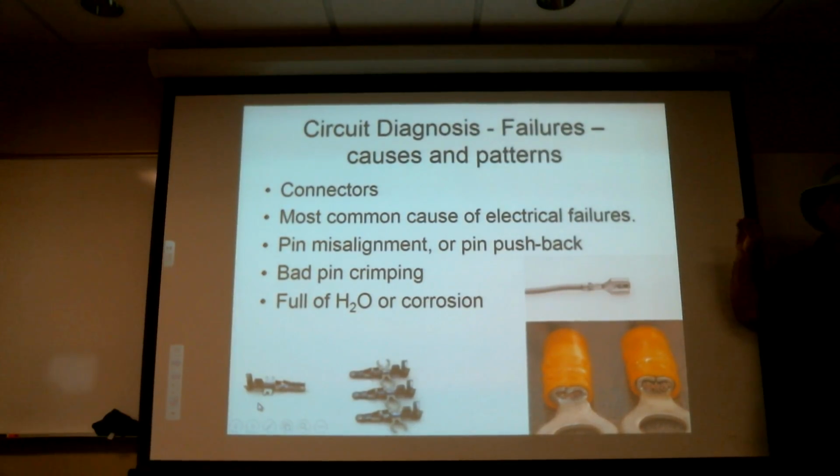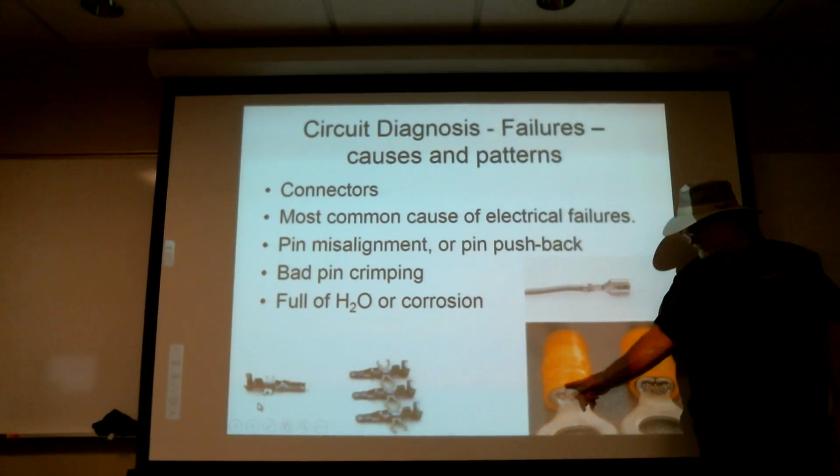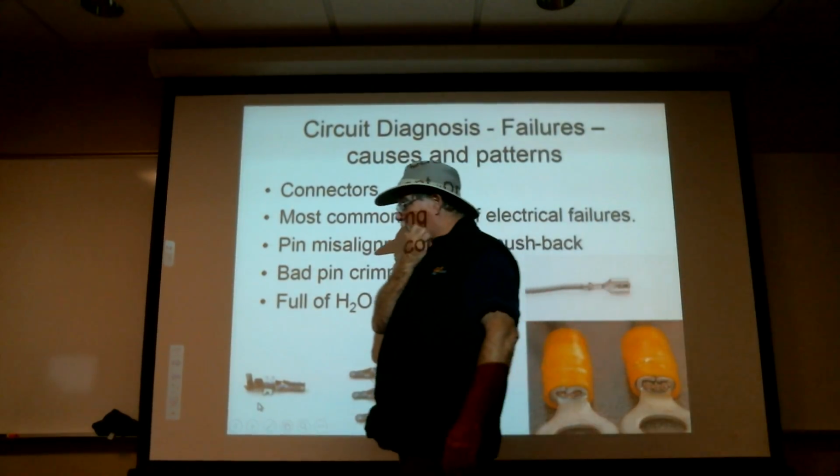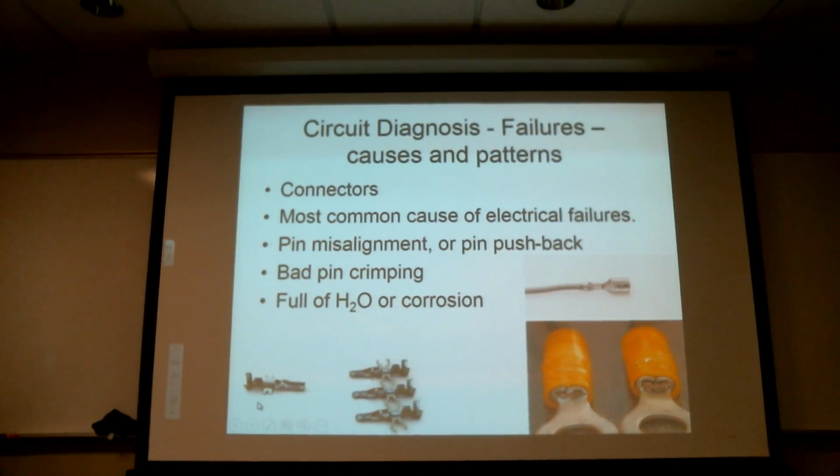This uses those mash type crimpers, which I don't use. They do a bad job. And this was just flat, probably putting the crimper wrong. And actually, in both cases, the yellow lug might be a little bit big for the wire that's in there. They might have wanted to go to the next size down.